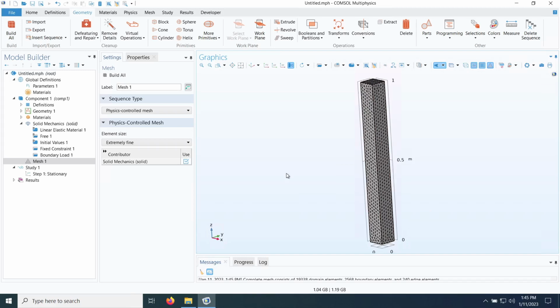But when you have very complicated simulations, especially if it's multiphysics nonlinear, the more elements you have, yes, you're probably going to have more accurate results, but also you're going to have to spend a lot of time waiting for your simulation to end. So there should be a balance. We usually do a convergence analysis. We run the model for different types of meshing and element sizes and numbers of degrees of freedom. And when we see a very small difference or deviation between the results as a function of element size, that will determine that we're probably safe with the bigger element size and less simulation runtime for our case.